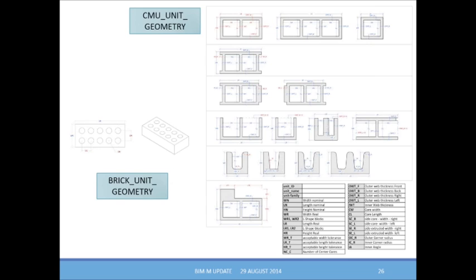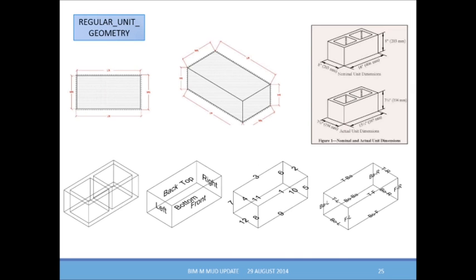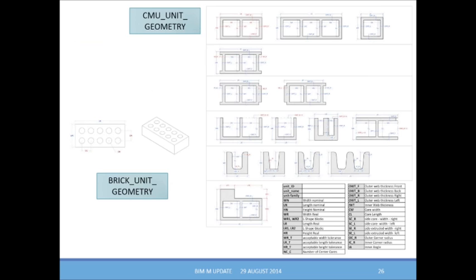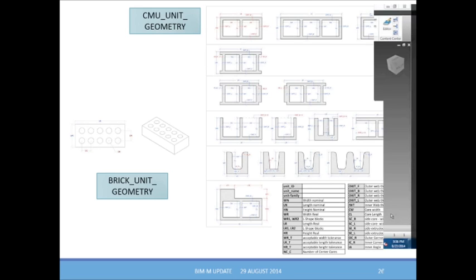And as Shani said, we have the standard regular unit geometry, which is ecumenical in terms of what material system it is, and then also specific parametric features which can be used to describe the wide range of shapes that are common in the clay and concrete masonry industries. These are just tabular data that describe the geometry of the unit. These features are not only used to generate the drawings of the masonry units, but also in certain cases, for example in structural engineering workflows, the structural engineer may need to know the face shell thickness or the web thickness, or the energy analyst may need that information. So all of that is extracted in tabular form and available in the database for those sorts of calculations.